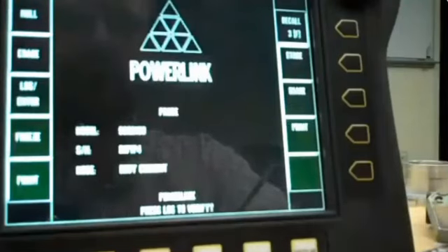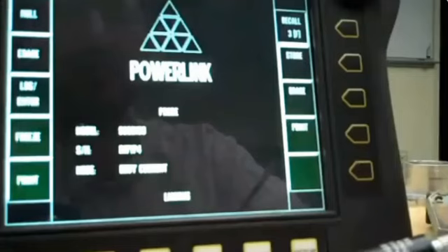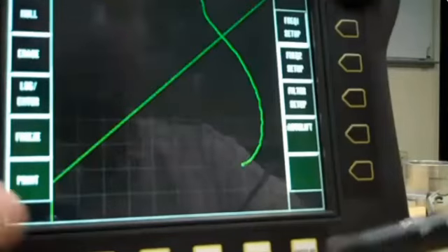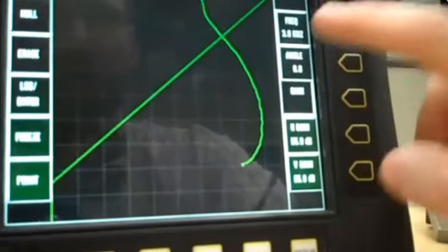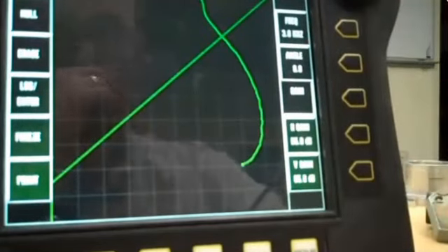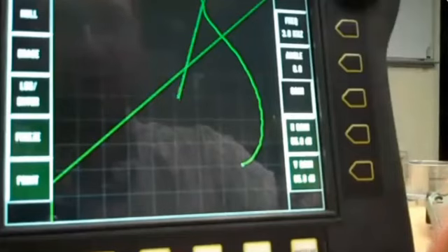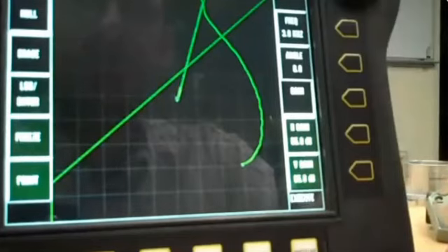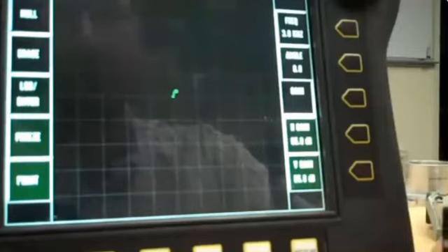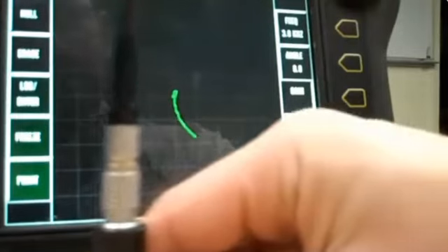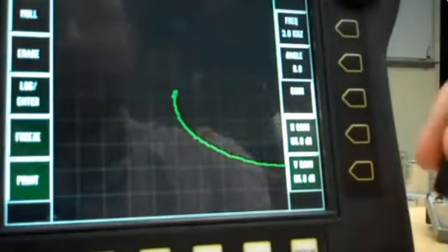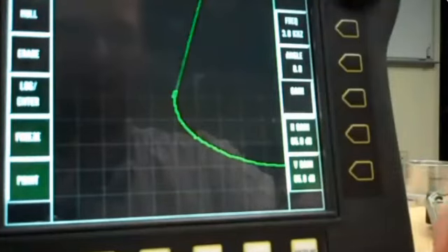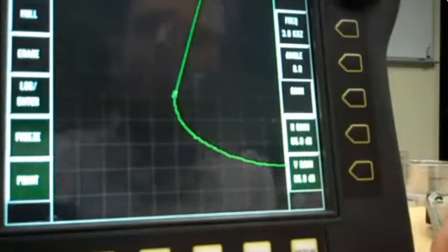Okay, now we're back. I'm going to push log so it knows what probe we're talking to. Go to main, frequency 1. It's already preset me at 3 kilohertz. That's good for now. I've got an angle of 0. Looks like it brought me back to the center. I just want to see where I'm going with this. I've got a signal that comes off to the right like that, but I want to set it up so it goes back to the left. I want it to look like my conductivity curve.